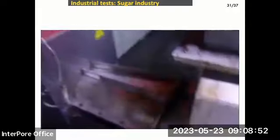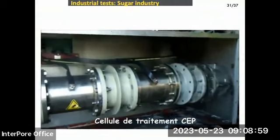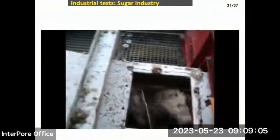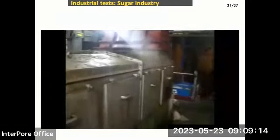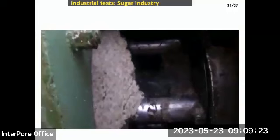And here, this is outside of the treatment chamber. And the treatment is done in this chamber, which is collinear, during the continuous flowing of the material. Here is the treated material. And then this material goes to the screw presses for better pressing. This is the screw press.